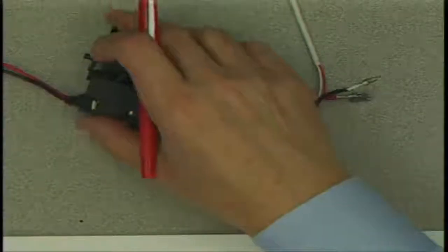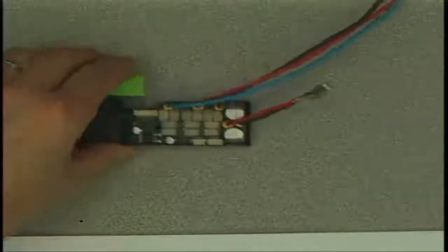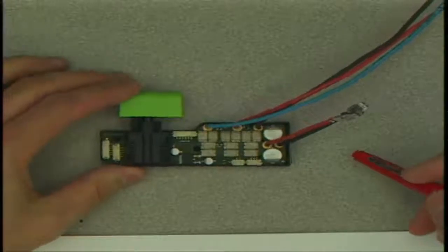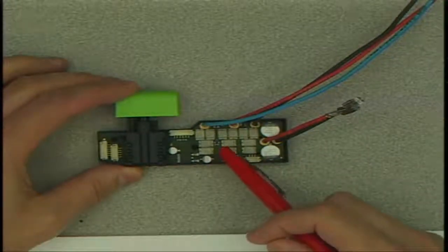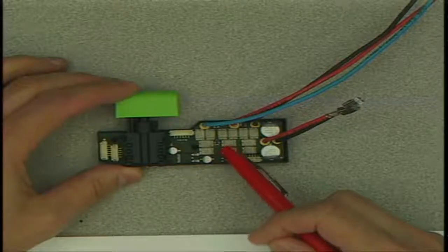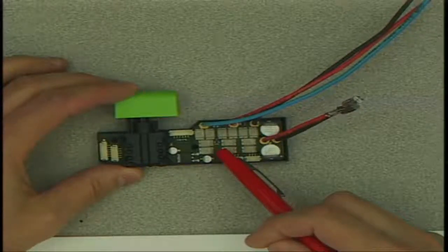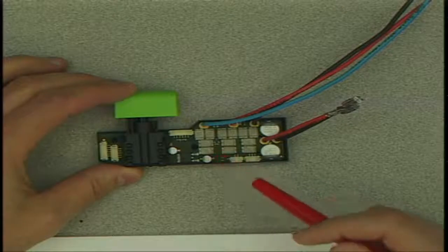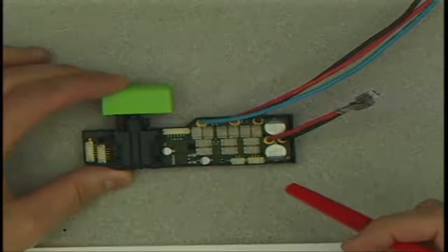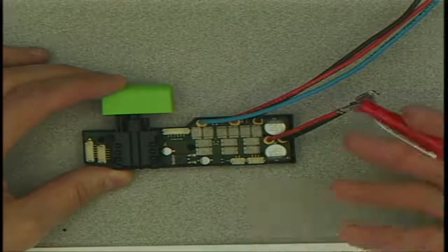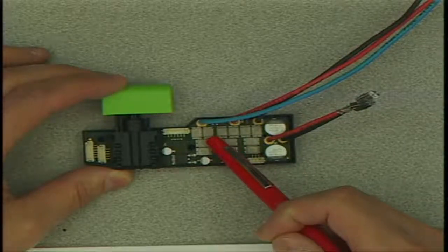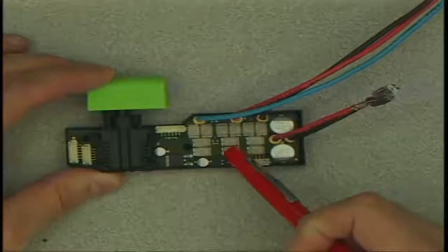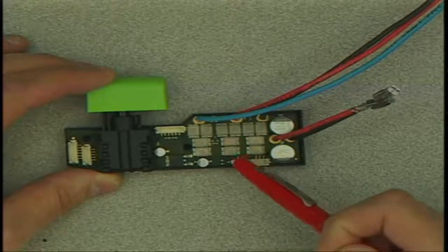And a more modern one, this is a few years old, more modern manufacturing techniques are now going to smaller packages. This is called a DirectFET package. The package itself doesn't have a lot of additional mold compound and wire bonds. The die is actually soldered right down to the board, and the can is sort of the cover that goes over it. So this is actually a brushless drive here.